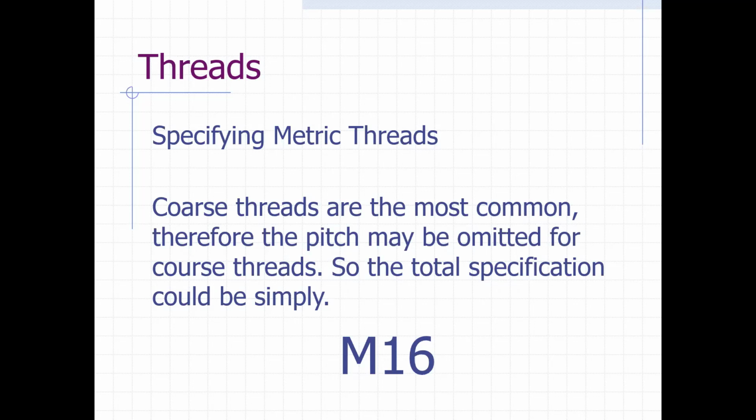But if you're using Inventor to put a threaded hole in or to put external threads on a shaft, then when you drop the list down, you'll see M16x2, M16x1.5, M16x1.25, and you're going to freak out and say, I don't know what to do. Here's what you do. You choose the one that has the largest number. That's the coarsest thread. So if it's 1.25, 1.5, and 2, which one would you choose?